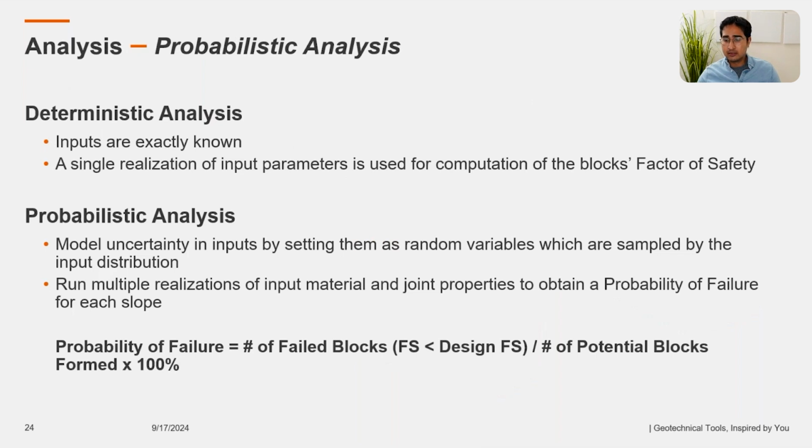Moving on from steps to create your model, I want to highlight some of the analyses which are accessible in RocSlope2. And like with our other suite of products, it is possible to perform a probabilistic analysis in RocSlope2, where the model inputs are essentially randomly distributed. There are multiple realizations of the model inputs, which are computed for each analysis method, and the probability of failure for each failure mode is reported.